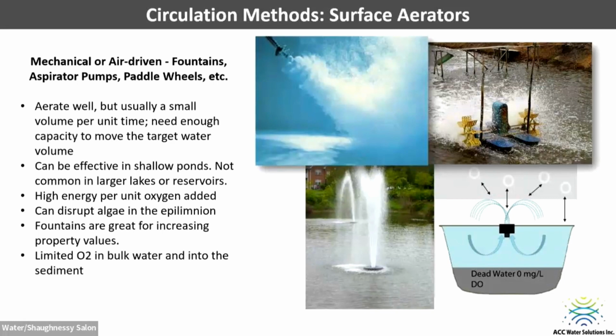All right. So circulation. With circulation, we're not adding oxygen directly to the water, or we're doing very, very little of it. Our goal is to take advantage of the surface transfer of oxygen, and it's primarily wind driven. So the limitation of all mixing style systems, no matter what they are, is that a huge amount of that transfer rate comes from trying to circulate the water body, and depending on wind speed, that's going to be the limitation you have on how much oxygen you get.